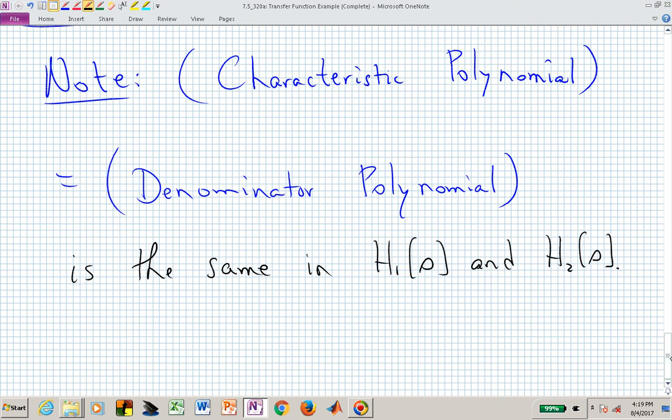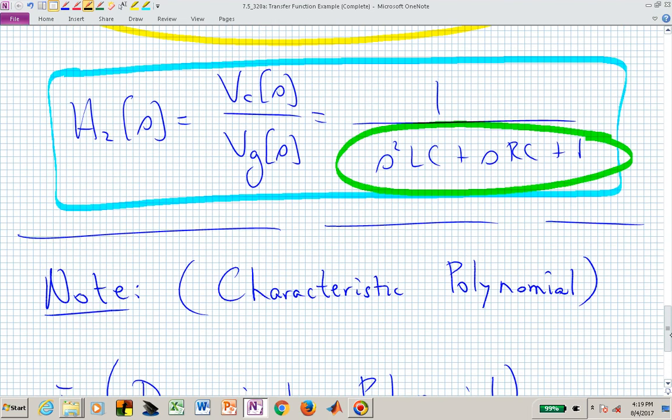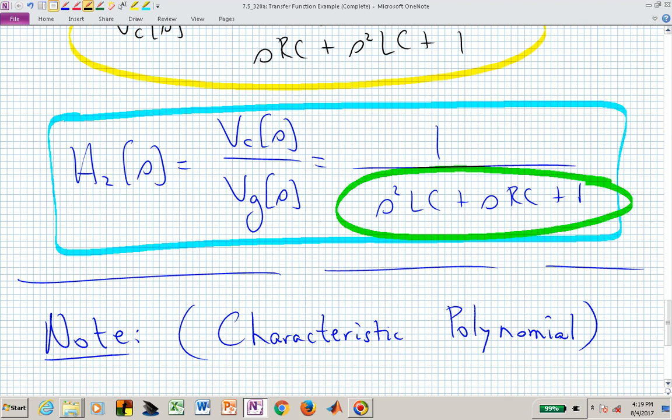The reason for that is because they are containing the characteristic behavior of your circuit. And that's then contained in the denominator polynomial. And remember, the roots of the denominator polynomial influence the poles, and the poles give you the modes of your system. So if you kick this system, it's naturally going to want to shake or move according to those modes or according to those poles.